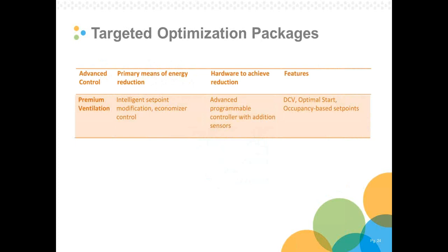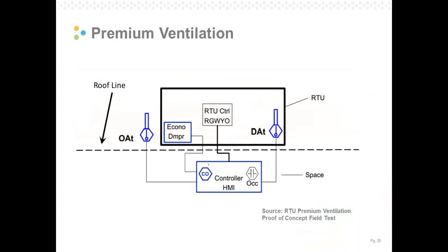Its features have demand-controlled ventilation, optimum start, and then occupancy-based set points. In our study, we used the KMC controller for the implementation of the premium ventilation.